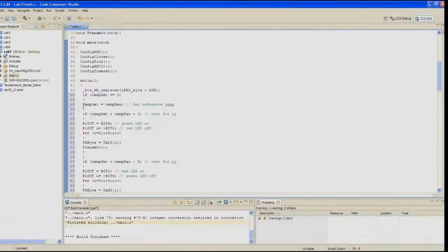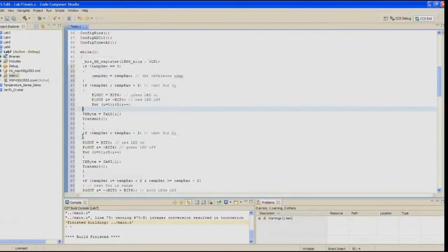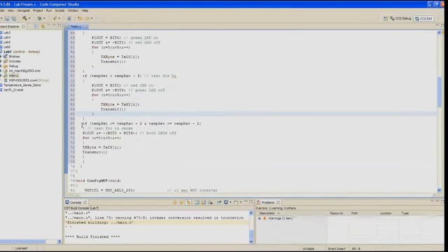So you can see we're using a preset of 5 degrees plus. If it's greater than 5 plus, or if it's less than 5 low, we're going to test for low, for high, or if they're both done, we're going to set for a 2 degree that's in range. So we'll be able to get all 3 of those situations, and that's what we're going to send over the USB port through the UART.